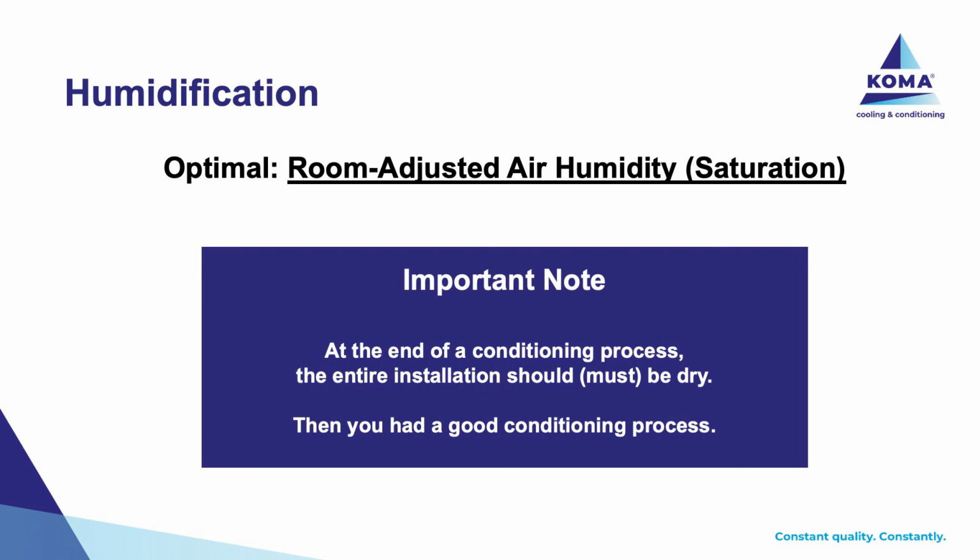Our principle of humidification is based on a very small delta T towards the room temperature. This means basically 1, 2, 3, 4 degrees higher than the room temperature should be the air humidified. This basically makes sure that the room doesn't heat up too much, so that your cold doesn't need to come in that often, which gives you an unstable conditioning climate. Therefore, the product is being formed and proofed in a very stable environment.